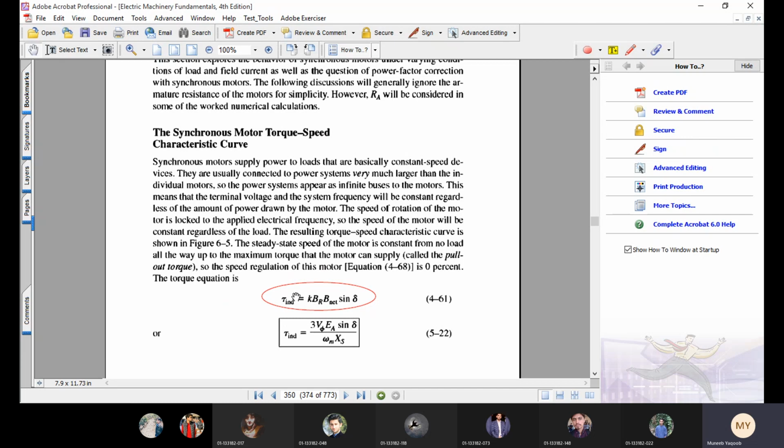So this is the phenomenon by virtue of which a synchronous motor runs at a constant speed. What happens is that as we apply excessive load at the shaft of the motor by means of an electrodynamometer, the rotor of the motor gets slow. But as the rotor gets slow, it lags behind the stator's rotational magnetic field with a larger torque angle delta.